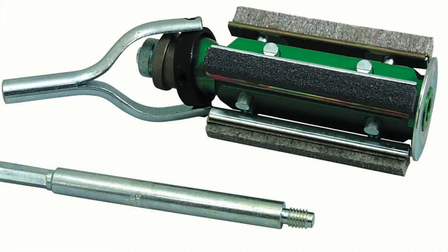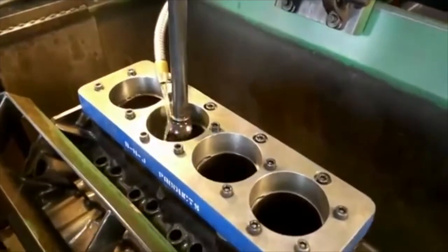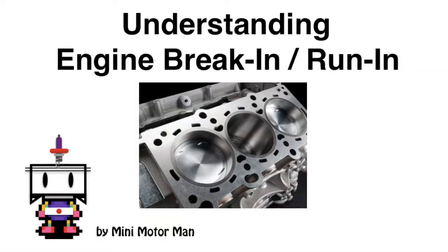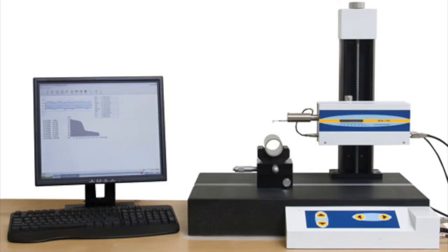which consists of a rigid stone-honed system like this, and a manually operated honing machine, or in small cases a drill press. Now, inexperienced machinists can still produce a very high quality finish with just their hands, so to speak, but being able to tell how skilled a machinist is going to be is largely unknown unless you're willing to shell out the money for a profilometer, which is this thing, and they're usually about £1,000 or more.